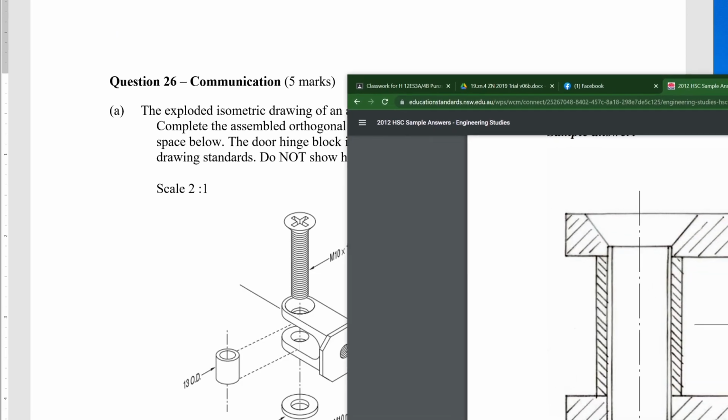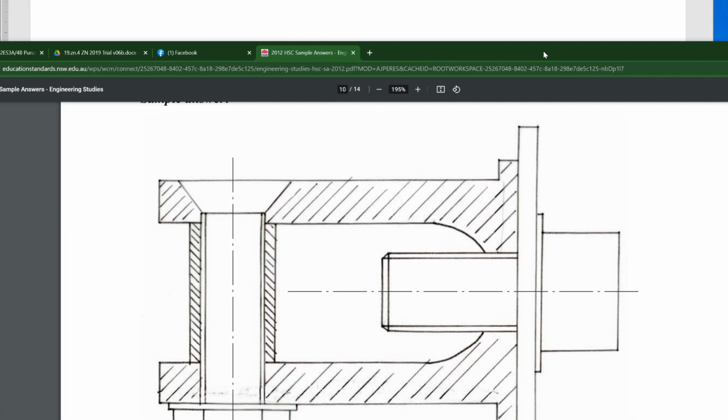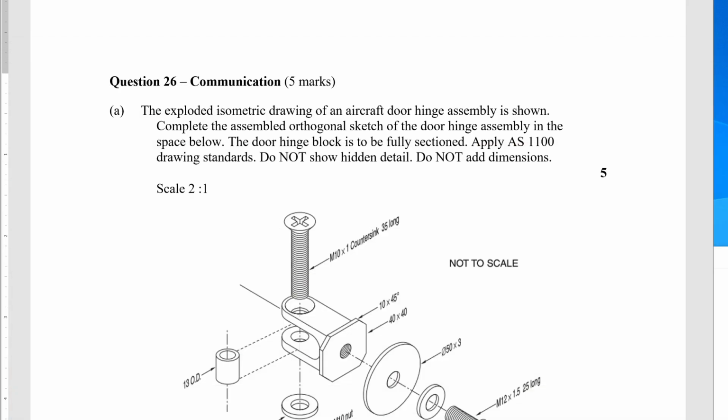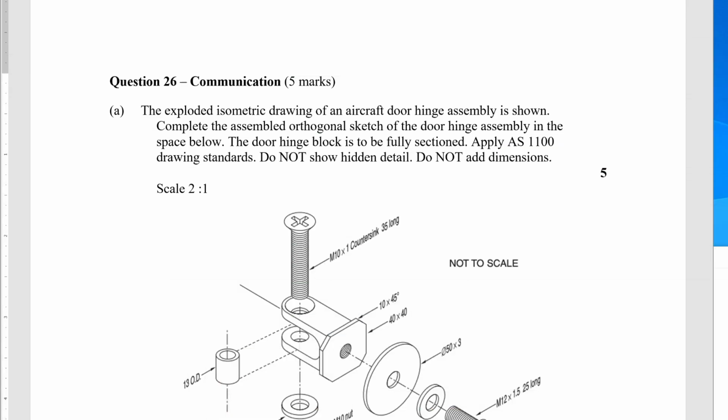That's what OD means. Now, we don't section washers. Even though we're going through washers, we don't ever section washers. And we can see here we've got a double washer, so that's why we don't show that. This bolt, with the Allen key hex nut and threaded section, they haven't asked us to section that. They've only asked us to section the door hinge.